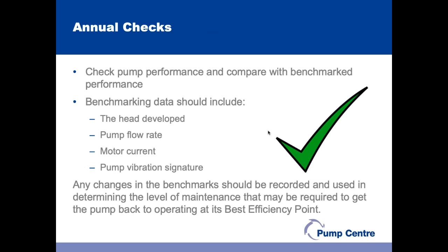And it's really useful to have that information available on day one, information such as the duty of the pump, the head and the flow rate, the motor current that's being absorbed, and if possible a vibration signature for the pump.